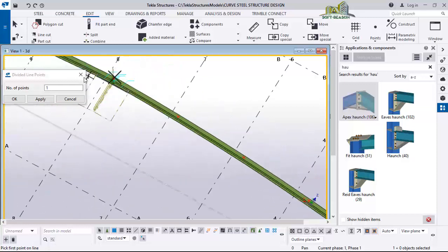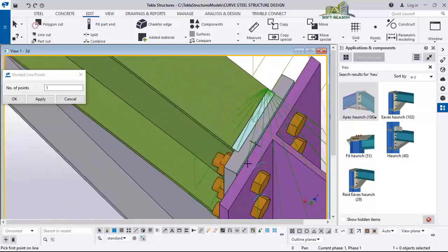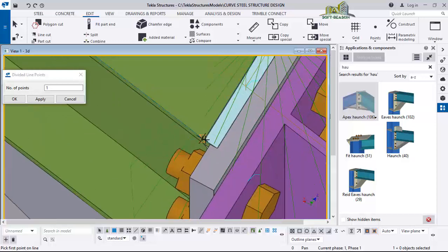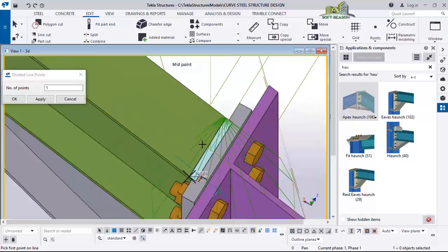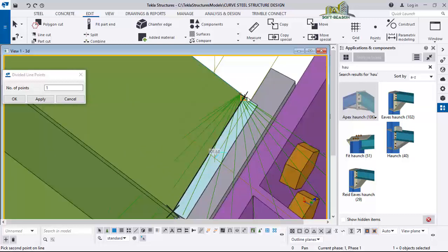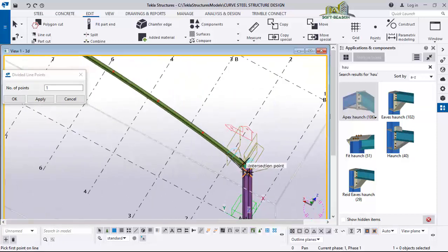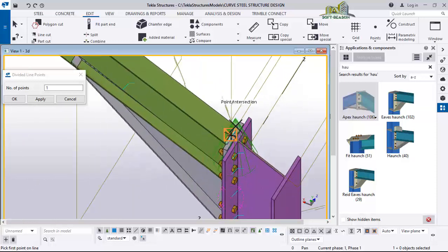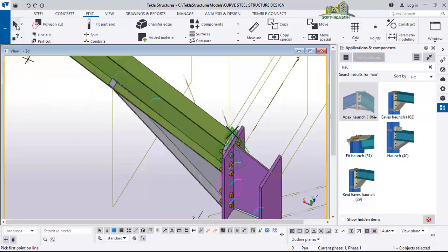Alright, the next place I want to be placing a point is I'll come down to the stanchion, this haunch. I'll pick this point, zoom closely so you won't make a mistake, that point and this other point. That's right, to place a point there. Okay, so what I need to be doing is I want to be offsetting this point from here, from this particular position upward 400 mm. So I click on OK here and select this command.